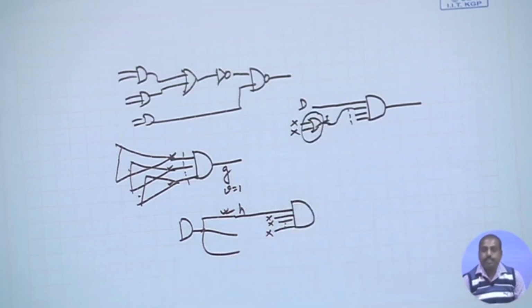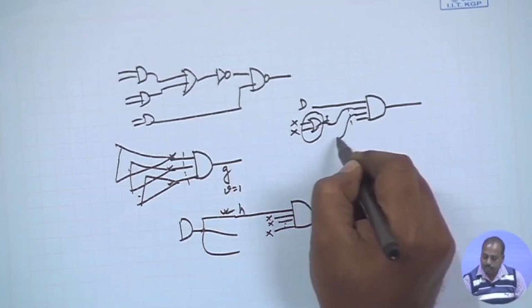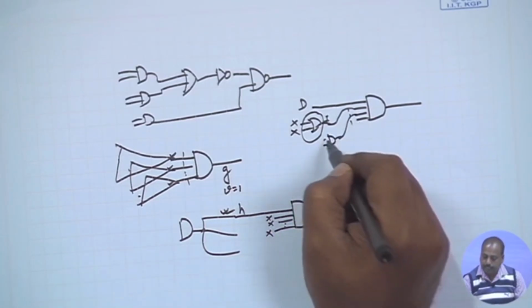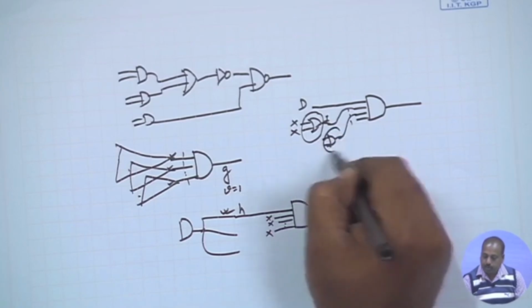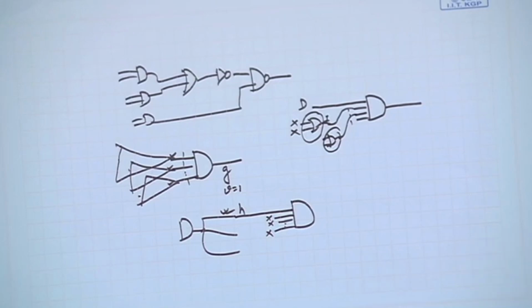So, this gate gets added to the J frontier. Similarly, if this gate is coming from say one AND gate, then this will get added to the J frontier. In this way, all the unassigned inputs of G will be set to non-controlling value, and they will be added to the J frontier.